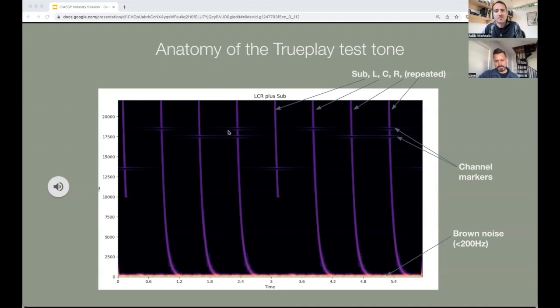However, some of our speakers, for example, the Sonos One, simply don't produce enough low frequency output to do this without hitting nonlinear processors such as limiters. Also, we would end up subjecting the user to fairly loud test signals in the room, which we want to avoid. Therefore, the solution to having a stimulus that would be robust to background noise in the low end was to have this periodic pseudo-random, band-limited noise to cover this part of the spectrum. This plays continuously for the whole duration of the sweep, so it gives us a better SNR than we'd be able to achieve with a simple sweep in this part of the spectrum, but it also gives us a better spatial coverage in the low end as well.